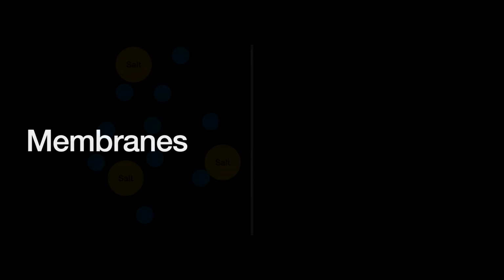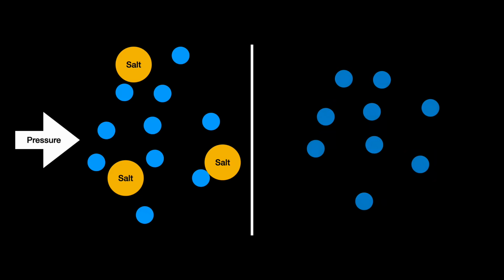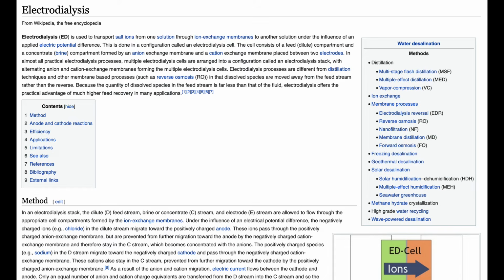Reverse osmosis is a membrane-based methodology. It uses electricity to push salt water through a semi-permeable membrane made of cellulose or nylon. High pressures are then applied to push water through the membranes. The salts get caught in the membrane while the water gets through. Other membrane-based desalination technologies include electrodialysis, which, without pretreatment, is only usable for brackish water and not full-out seawater.